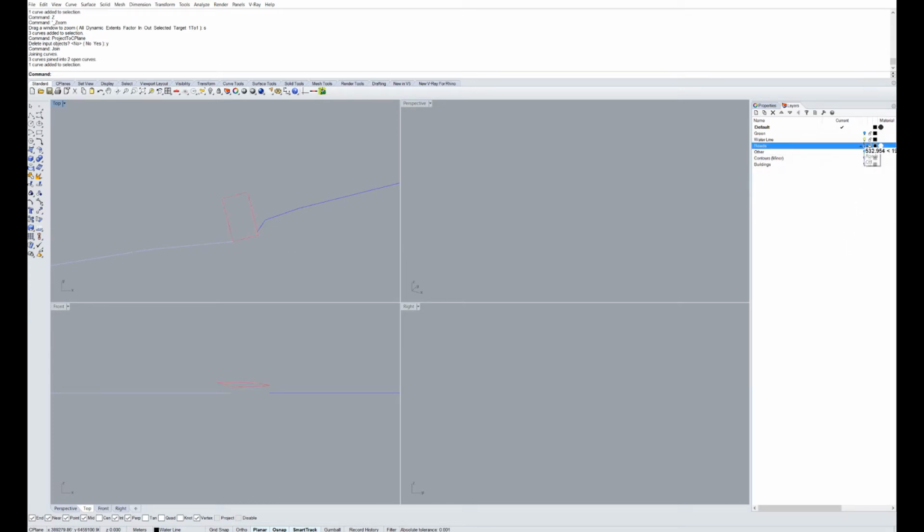If we select roads here, we notice there is a bit which looks like a boat ramp, and I'm going to assume that the waterline goes around it. So I'm going to select waterline as my current layer, and select polyline, and I'm just going to draw around it.